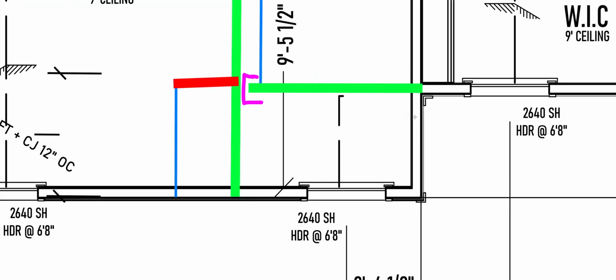So I've got rafters starting at the wall. They're coming up to the ridge right there. And I want to brace them on this beam. I could draw a line on this, but it doesn't look as clean. Effectively, that's where I can put my braces, but I'm just going to symbolize it with this guy here. I want this to be braced to this beam. So what I'm saying is this is a purlin now. This is a board that is going to be turned horizontally in the roof, and it's going to go up underneath the rafters and be braced to the beam.